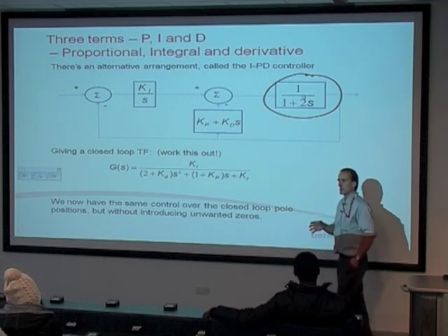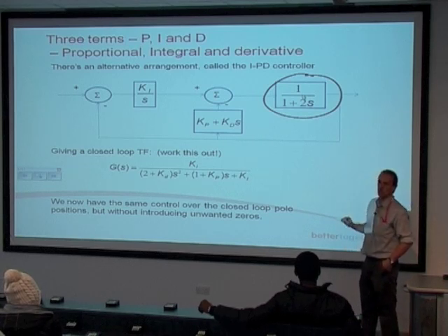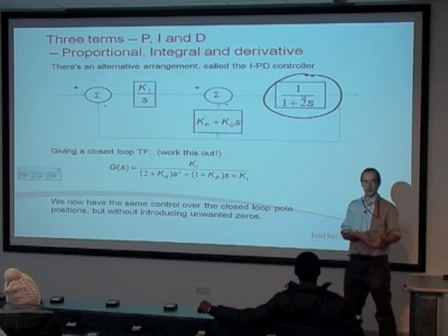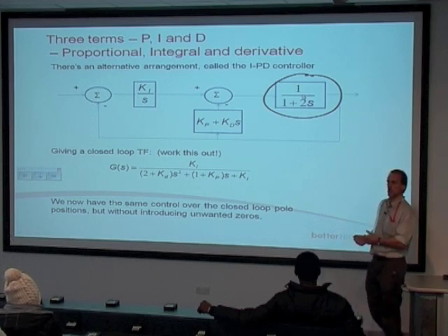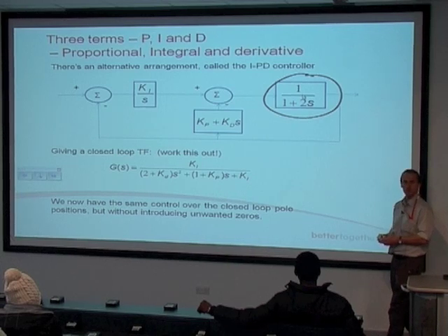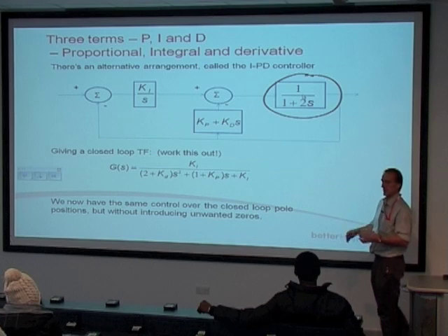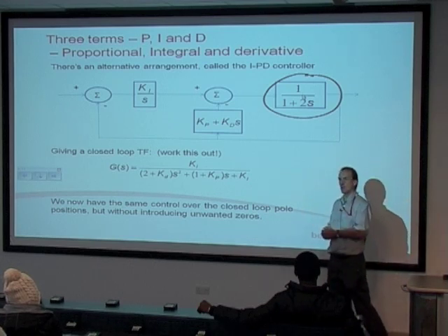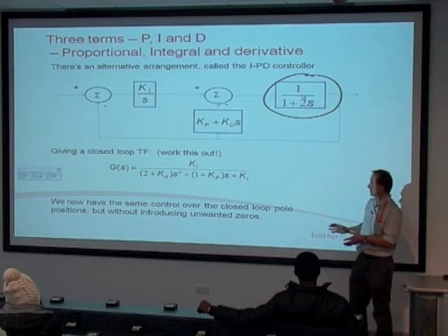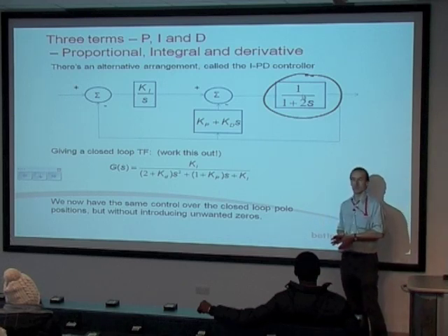But if you're in a situation where you don't have that model, and maybe you haven't got the facility to do a quick frequency response test to evaluate the transfer function, that's when the empirical tuning methods come in. Okay, because fundamentally you're tweaking things to see how the real system actually behaves and basing your values on that.